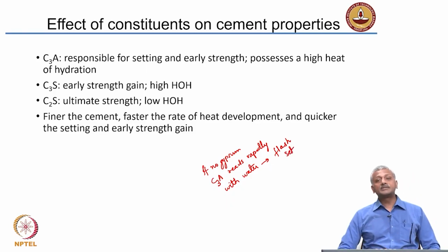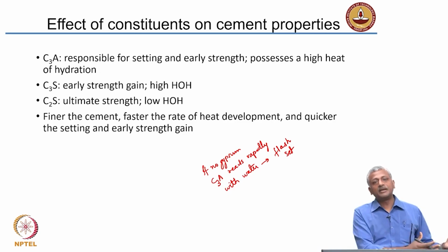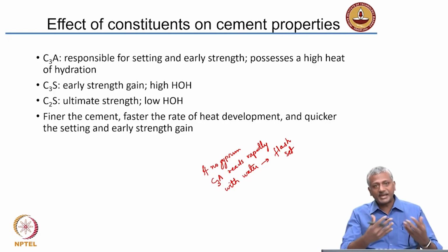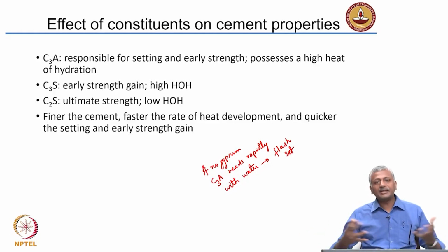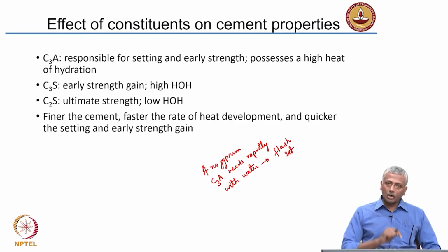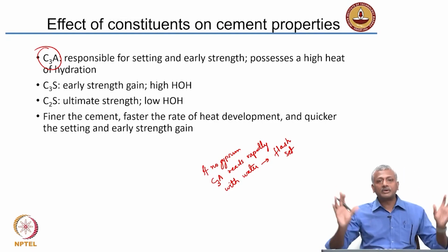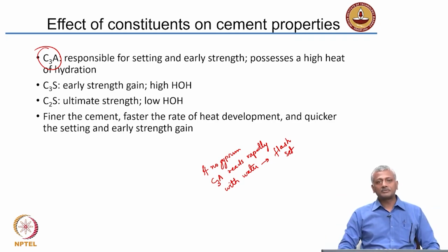So, in other words, the cement without any gypsum, when it reacts with water, you will lead to a condition which is called as flash set. That means it will suddenly harden and it will not be recoverable beyond that. That is why we want to add gypsum to take care of C3A, otherwise the C3A will go crazy. Okay? Without gypsum it will go crazy.